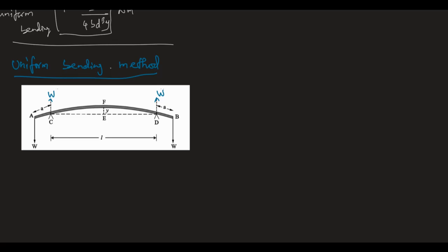So here Y is the elevation. Earlier in non-uniform bending there is a depression, as in a cantilever, but in this case it is an elevation. Okay, now I have to get the external bending moment, because I am giving the load W on this side, which is to get the proper arc, how much it is making. If you see this, it is like a couple.